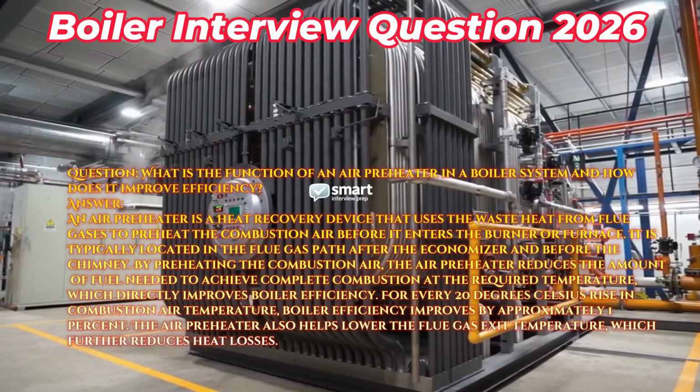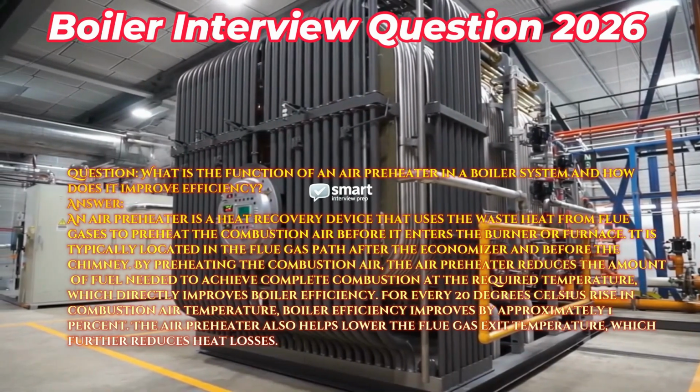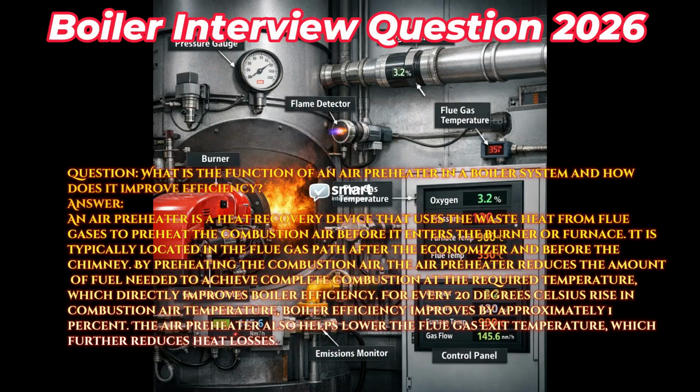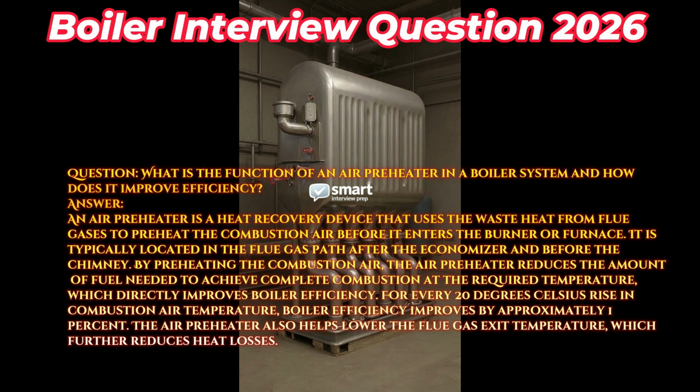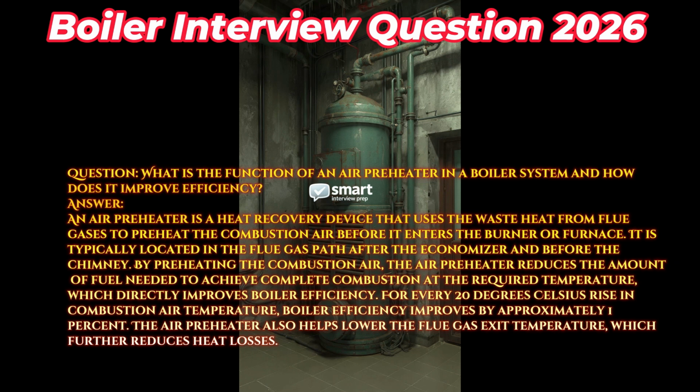By preheating the combustion air, the air preheater reduces the amount of fuel needed to achieve complete combustion at the required temperature, which directly improves boiler efficiency. For every 20 degrees Celsius rise in combustion air temperature, boiler efficiency improves by approximately 1%. The air preheater also helps lower the flue gas exit temperature, which further reduces heat losses.